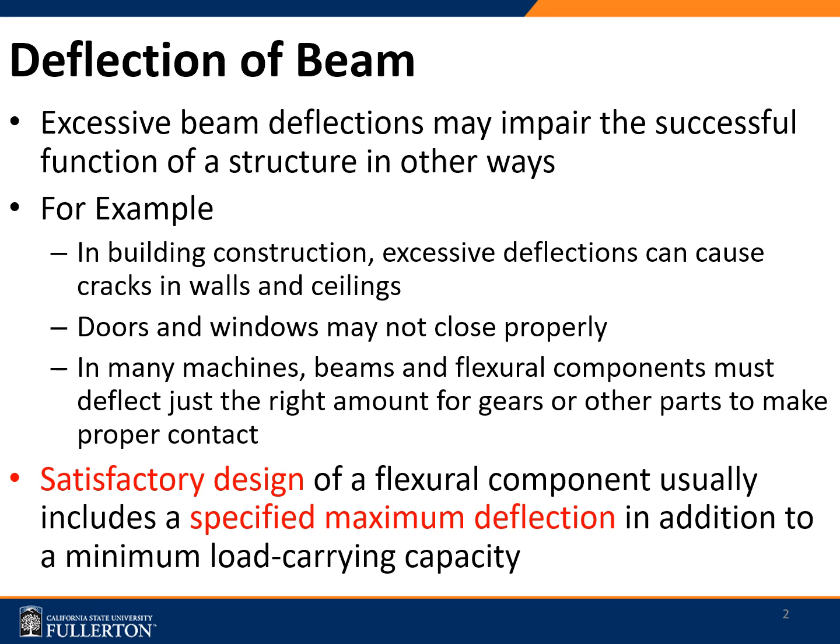Now, the excessive deflections. The beam always deflects. So beams are designed to deflect. If it doesn't deflect, it would break. So what we are seeing here is excessive deflection. That means a deflection that is causing concerns for the designer as well as for the people who are using that particular structure. Let's say a door, because of the deflection, it doesn't close. That's an excessive deflection.